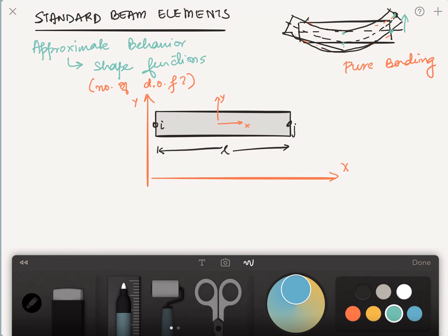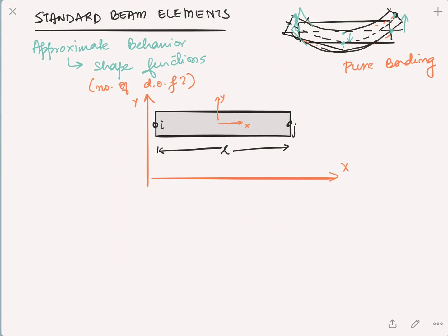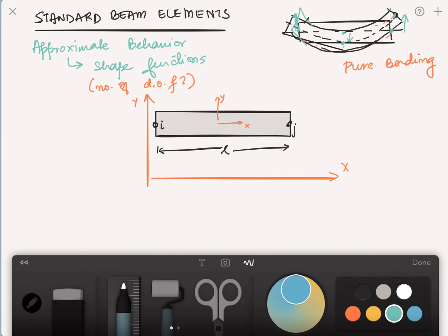This point right here has moved downwards. This point has again moved here. Sorry, this is not a very good picture. If we look at these two parts here in the drawing, this one and this one, then we can see that there is vertical displacement happening. Therefore there will always be this degree of freedom which is vertical, or called transverse displacement.